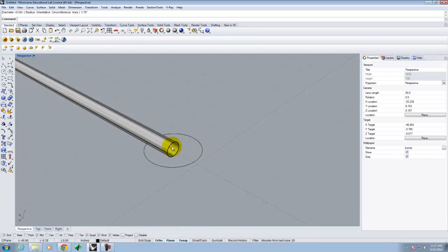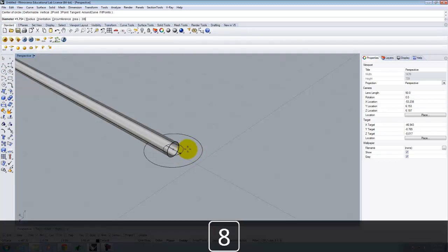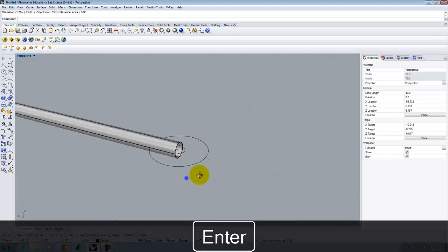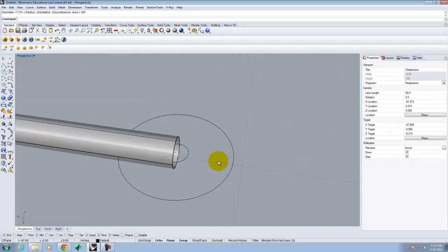Okay, now the inside is 3/8. So I'm going to create an inner circle that is 3/8 of an inch. So again, the diameter, and I'll do 3/8, like that. I'm purposely giving you different sizes in this because it makes this a little bit more challenging.